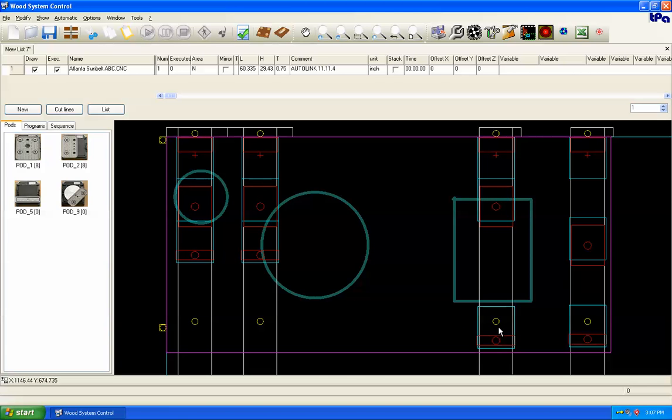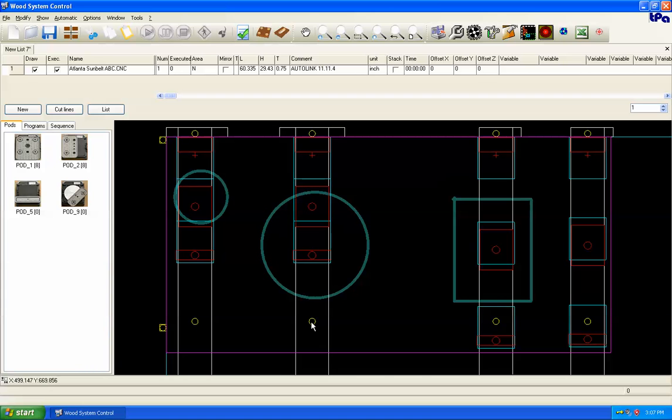What you see here in yellow, these circles at the back and on the side, those are the reference pins. And the pods are drawn with two colors. The red represents the vacuum cup that's directly touching the part, and then these particular cups have a base that's shown in blue, and they're offset. So the red is what we do not want to put underneath the tool path or a drill. And the base, that's not as important as far as staying away from the tool path.